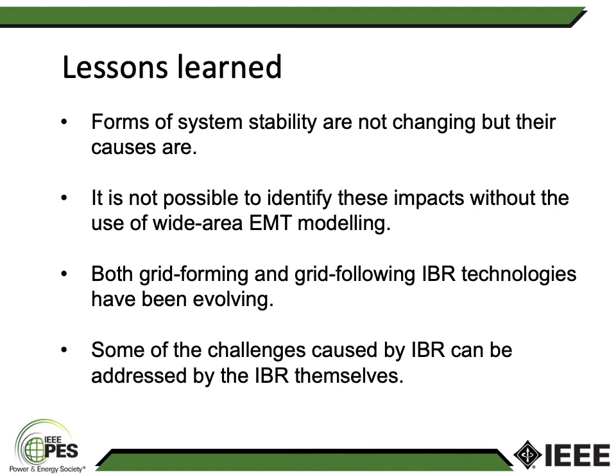Also, what we learned is that grid following inverters are improving and their performance is evolving. And then we are also, in parallel, having grid forming inverters that collectively could help address many of the system stability challenges associated with increased penetration of inverter-based resources, and that we don't need to have a synchronous machine in the power system to address every single stability issue.